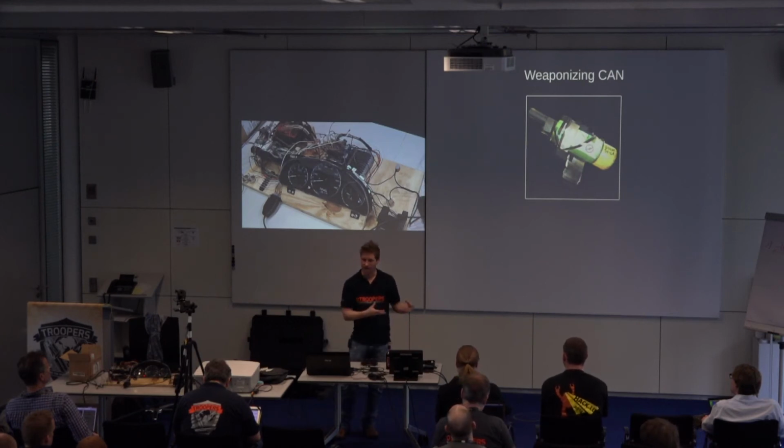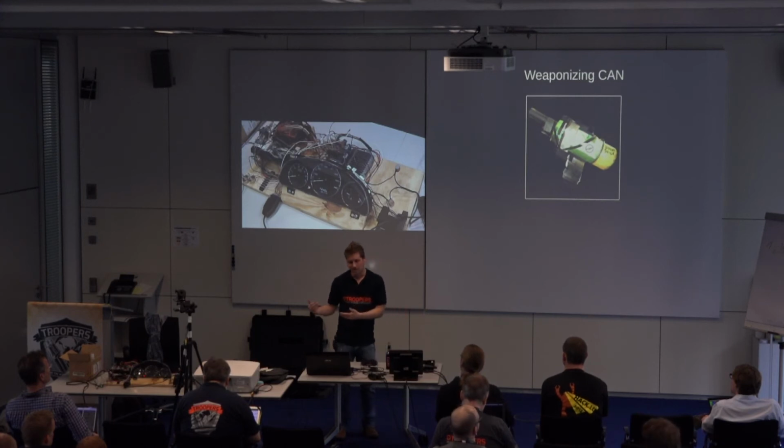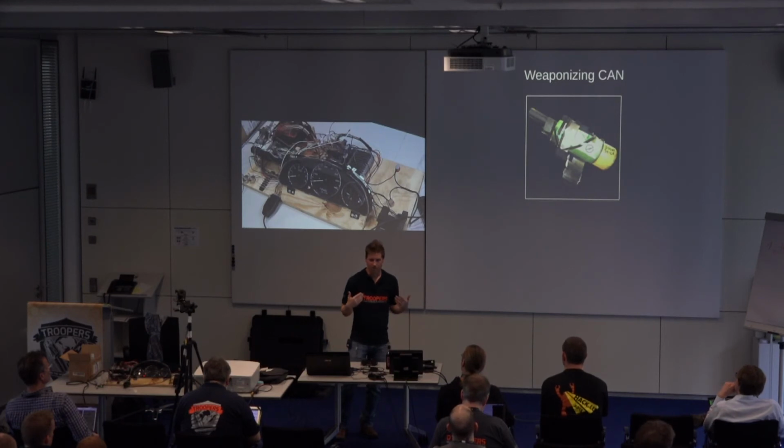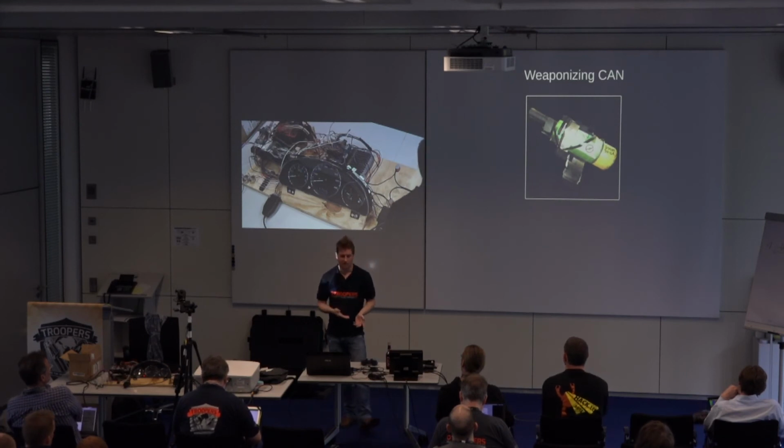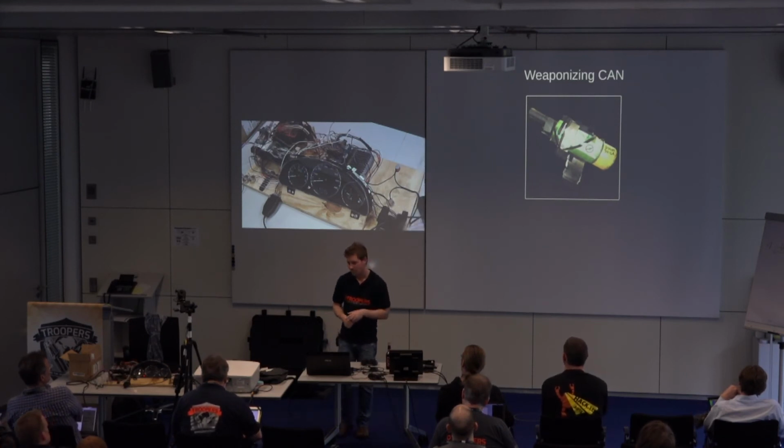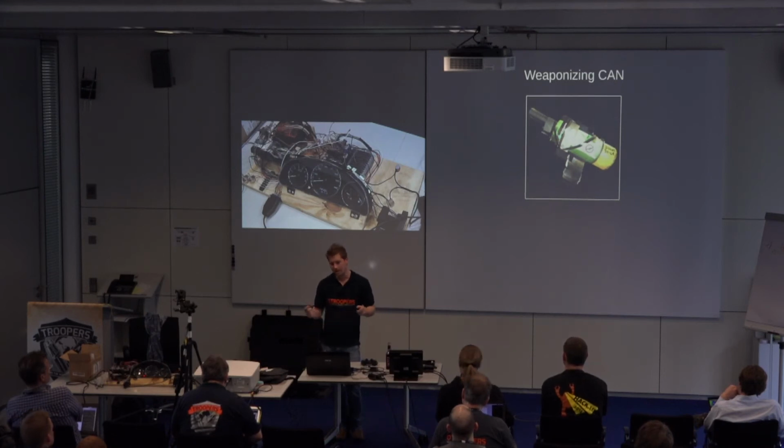Is it a clunky CAN device on the sensor side? If you can see that the CAN packet is being sent that controls the window, and it's not going down, you can quickly identify that it's CAN. But because it's 25 grand per make and model, and if you work on more than one make and model, you're not going to be able to afford that. So mechanics need to reverse engineer the stuff. They need to have that information as well. The current workaround that I've seen is that people will take stuff from Alibaba, some cheaper devices where they've reverse engineered some of that information, and then you can go through the tools that way.